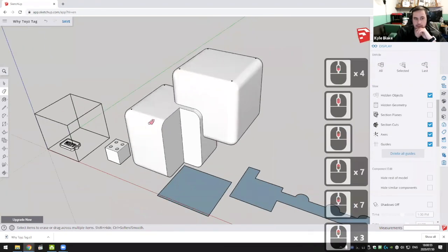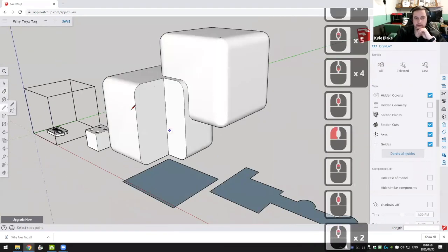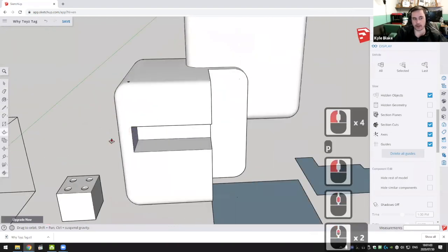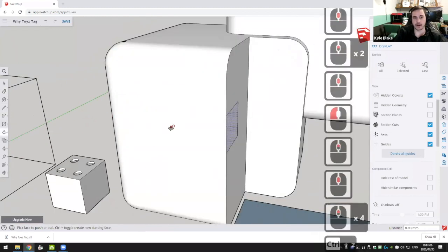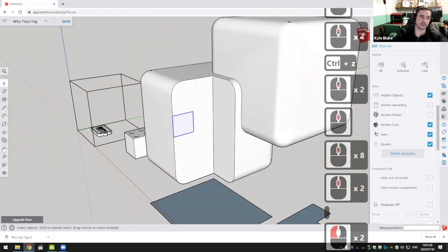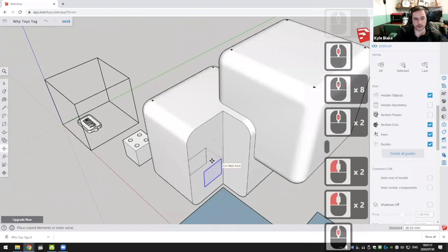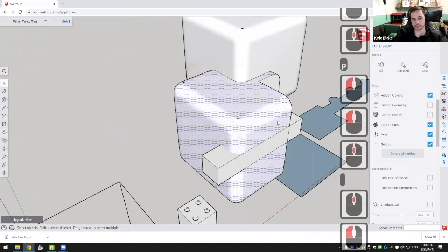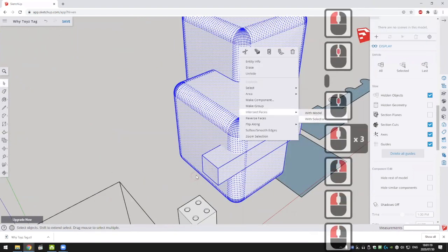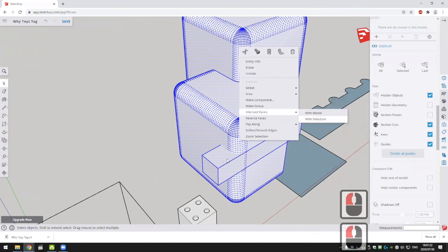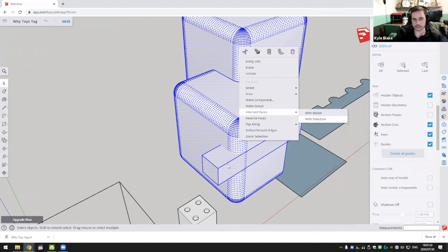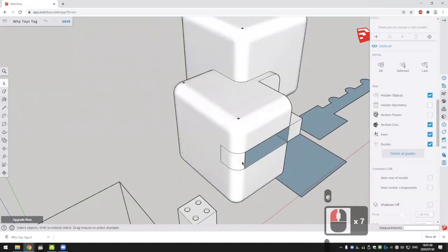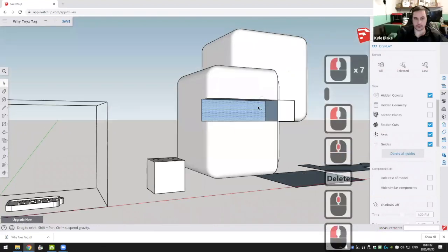It was basic shapes and then cutting out pieces of it. But when you get to corners here, it won't let you cut past it because it's now a rounded edge, so you've got to think about that differently. If I create a new model and push this all the way through, I can then intersect it and cut it out. This is a little bit slower though, but you end up with something like that.